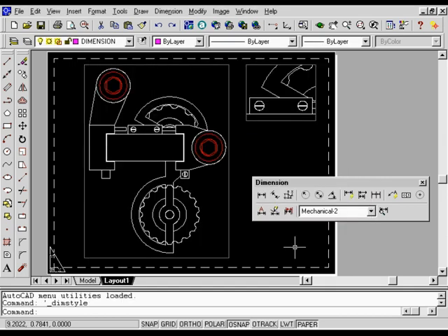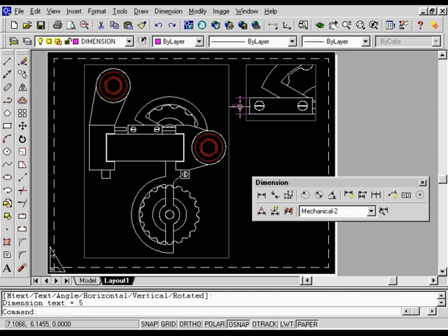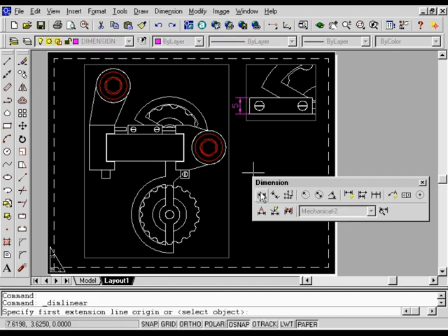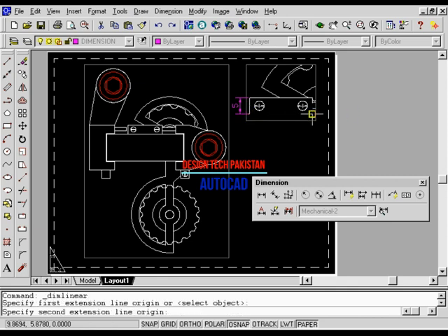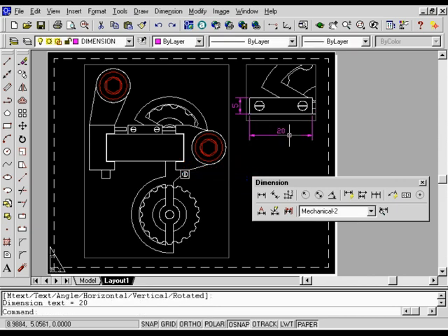Creating linear dimensions using the new style. On the Dimension toolbar, choose Linear Dimension. Press Enter, and then select the vertical line on the left side of the detail. Click to the left of the line to position the dimension. On the Dimension toolbar, choose Linear Dimension. Select an endpoint of the lower horizontal line adjacent to the existing dimension. OSnap is turned on, so your cursor automatically snaps to the endpoint of the line. Select the opposite endpoint of the same line. Click below the line to position the dimension.